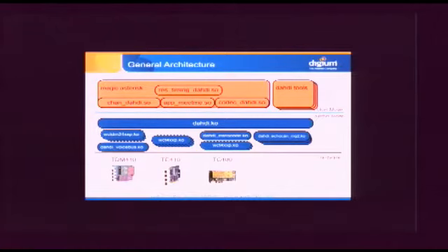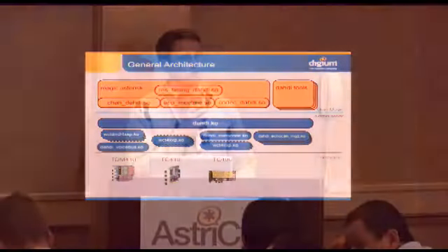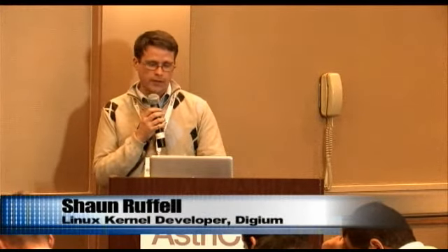Also, some of the board drivers, like on the DAHDI voice bus on the bottom left, use common libraries that are used amongst different board drivers, so that's what that's representing. And that's actually what's talking to the physical hardware. There's also the transcoder, the TC400. It uses a separate DAHDI transcode that allows transcoding channels to be advertised between different transcoder cards, and that's what it does. And then there's also a collection of modular echo cancelers. So most people, if you're just doing a default install, you're only going to have DAHDI EchoCan MG2 installed, but there's other ones available that you can use.